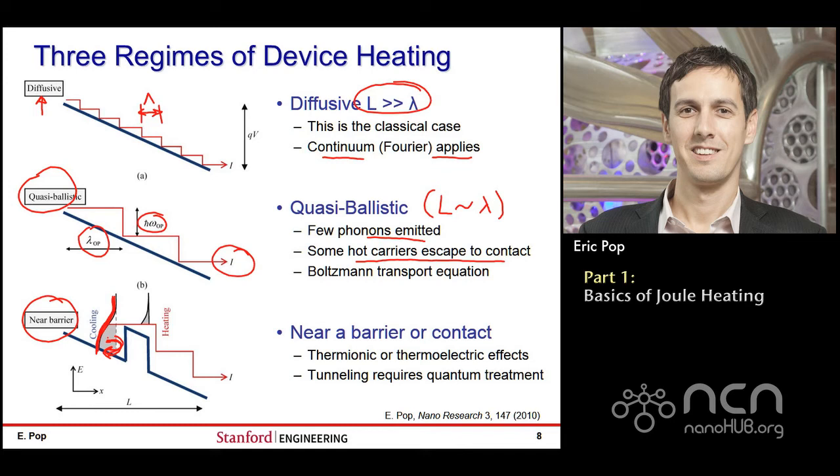On the other hand, electrons that have energies over the barrier will be able to thermionically emit over the barrier. So you can imagine the barrier acting as an energy filter, such that only the electrons with energy greater than the barrier height will be able to transmit across this barrier. And therefore, the distribution that is left to the left of the barrier will be significantly colder, right?